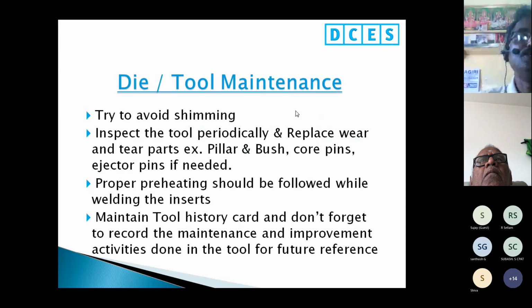Try to avoid shimming. Shimming means sometimes you put a shim underneath the ejector pin, core pin or the inserts. Sometimes what will happen, the shim will jam and it will create a dimensional issue. So always try not to put any shim inside the insert.